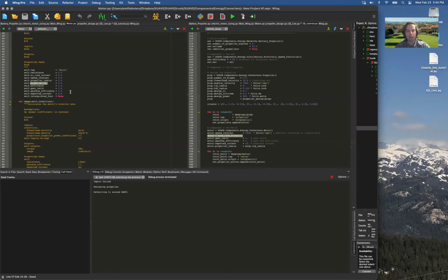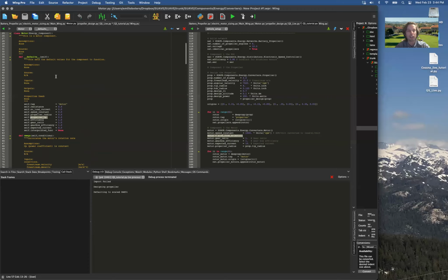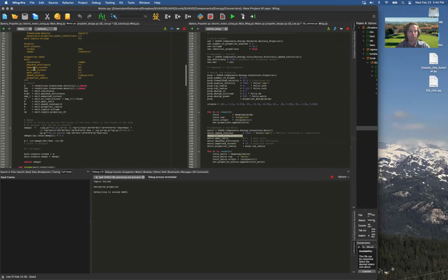If you're unsure, the best place to check is in the component itself. It'll tell you, and if you're not sure, put in everything you can. And if it gives an error, usually if something is defaulted to 0 and there's a division by 0, that'll come up later on. But there's more than one way to do all these things, so unfortunately, there's not one set rule. The best way is just to look at it and say, hey, it's going to call all these things, so I need to specify them one way or the other.